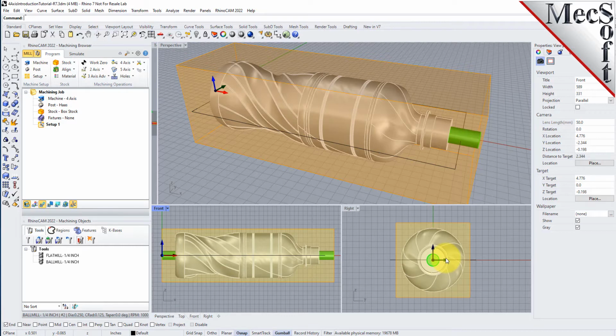The actual stock on the 4-axis CNC machine will be rotating along the x-axis. Once the second 3-axis horizontal roughing operation is complete, we will then create a setup 3 that will index our rotary table back to 0. Then we will program our 4-axis parallel finishing operation. During this operation, the rotary table will index a full 360 degrees to finish the entire part along the x-axis. So if you're ready, let's get started.